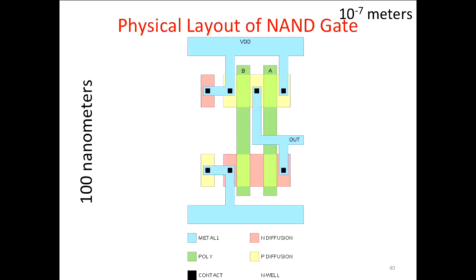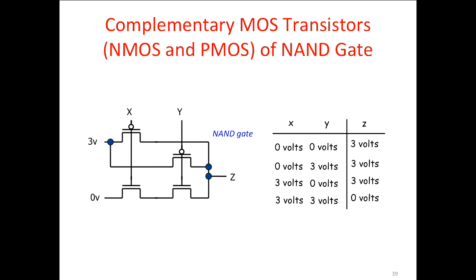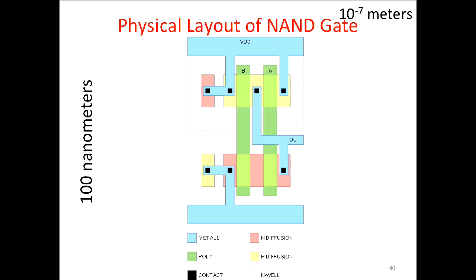transistors. These are the 2 pull-up transistors here. So VDD on one side, and this is their common node here, comes out. These are the 2 pull-down transistors. These are connected in series. So this is ground here, contacted here, and this is the output here, and this is the series connection here. These are the 2 transistors. This stuff is the gate material, polysilicon.